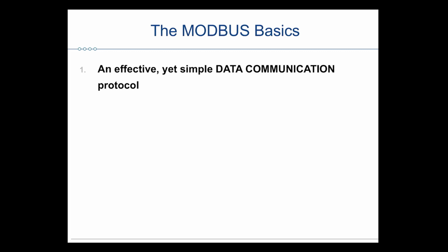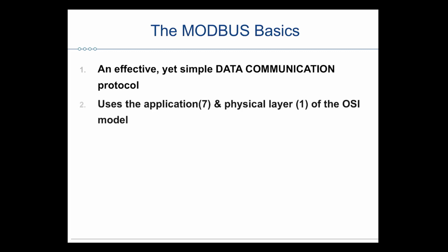I often say that because of our inexpensive high-speed connections these days, we can afford to be wasteful with our bandwidth, and therefore Modbus still has a real foothold in a lot of these networks because of that. You don't need to bring in the complexity of something like DNP3 when you can be wasteful with your bandwidth. That's the best way I can put it.